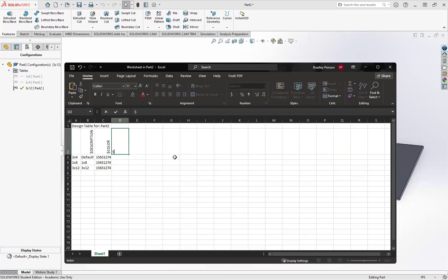So for equations or global variables specifically, we're going to have a very specific syntax we need, and they all start with a $ sign. The $ sign, and in this case, it is value. We want to change the value, so we use an @ symbol. And first up is going to be height at equations. So that tells it to look for the height variable in the equations in the model.